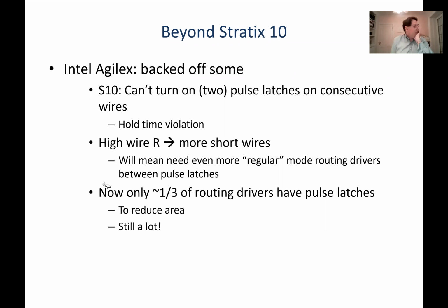Okay, so what's happened since Stratix 10? Stratix 10 is Intel's latest shipping FPGA, but they have announced another one called Agilex, which isn't shipping yet, at least not broadly, but they've published some details of how it works. And they've backed off the put a register or a pulse latch on every single routing driver.